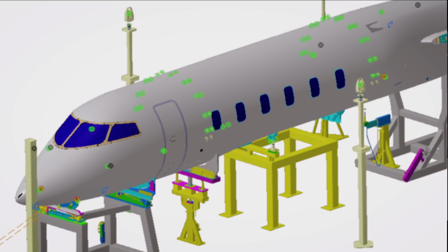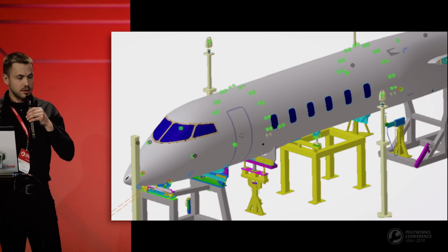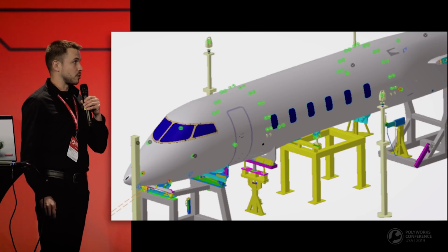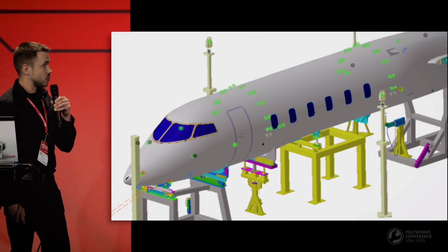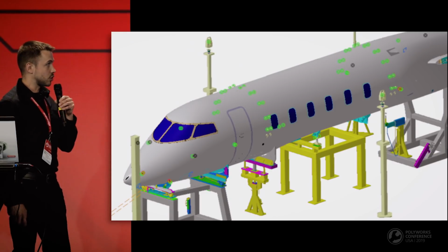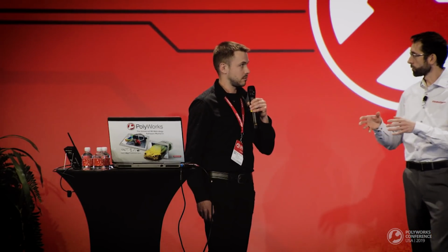So we created a new program with the 2019 version of PolyWorks to simplify the large macro script with sequences and an object measurement script. To give you an example, the large macro script from 2018 was reduced to six sequences and one object measurement script, to have an automated solution that meets all our requirements. So it's not only the object measurement script that was the key here, it's also the use of measurement sequences. Yes, you are right.